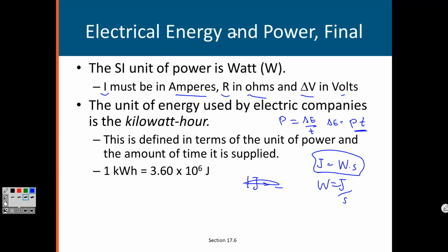So that's why it is practical to define another energy unit called the kilowatt hour. See, 1 joule is 1 watt second, right? If you use an appliance with 1 watt power for 1 second, that will be 1 joule. An appliance which draws energy at the rate of 1 joule per second, used for 1 second, consumes 1 joule of energy. This is a very, very small, minute amount of energy. So the practical unit, if the electricity board wants to charge you, is the kilowatt hour.